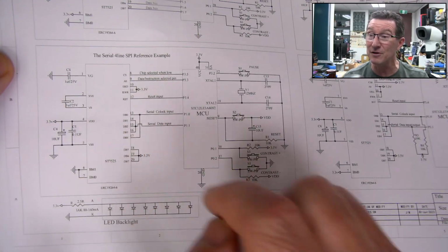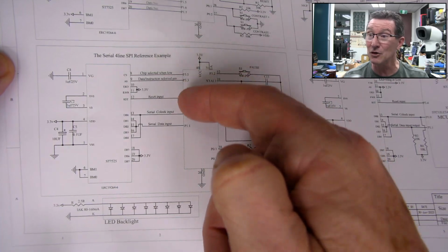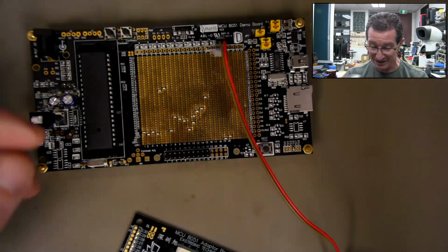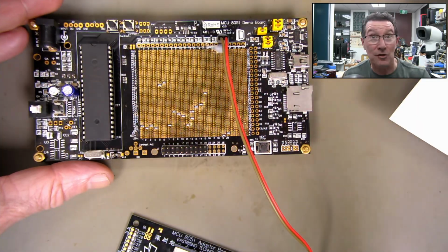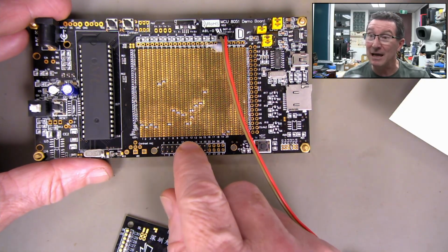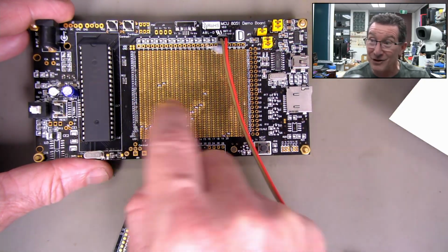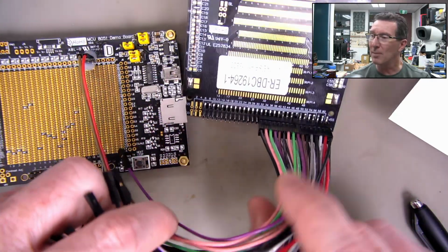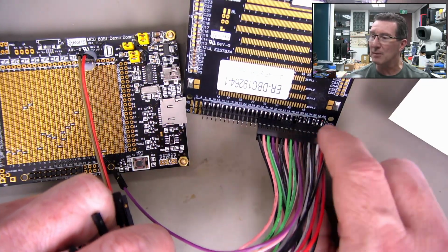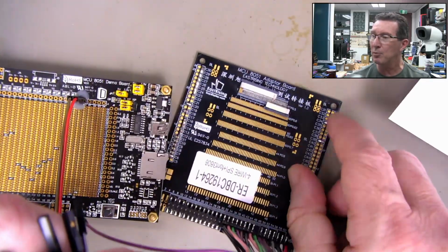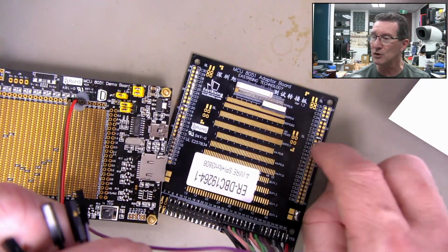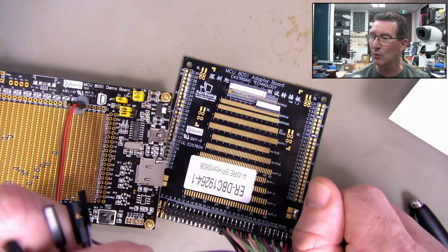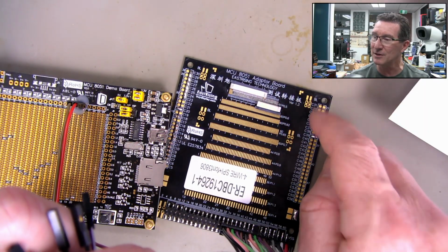And so we only have to, in theory, hook up 4, 5 pins to here, plus the 3-volt power and ground. And then we hook them up to the right pins on this via this selection matrix. I've just got a wire bundle here, so I'll be using these pins over here. I'll tie some of those caps on here, and I've got all those pins coming out to this one side.